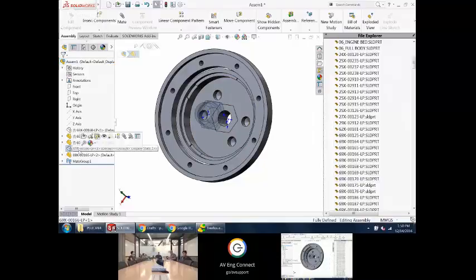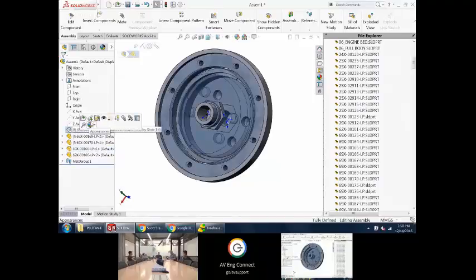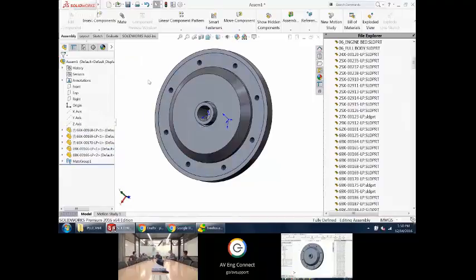Would you recommend locking rotation when it doesn't? I have been locking rotation just because they put it in there. It's nice to do. It's not crucial, but especially because, when we start rolling up into subassemblies, if that subassembly is flexible, it's not solving for it anyways. Yeah. So it's not like it's going to build up if I have every screw able to rotate. It's going to kill me at the top level. Mm-hmm. If you've got it in subassemblies, it won't. If you don't, it will. It's a good idea to have subassemblies because you put in a little bit of a shock absorber as far as how much calculation it has to do. If the thing's coming in rigid, not much calculation at all.